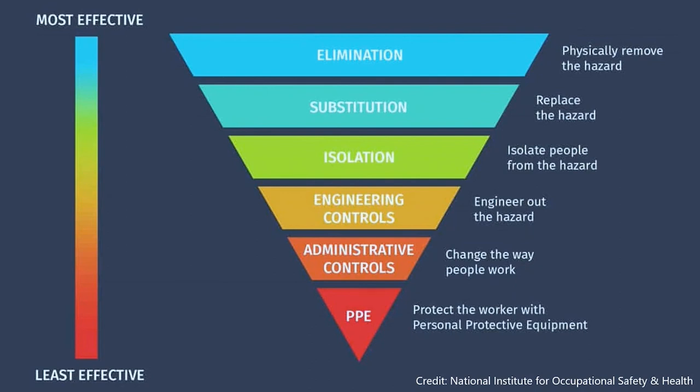What is the value of an engineering control in terms of its independence and its probability for failure on demand as opposed to an SOP and operator intervention? What is the benefit to having a process that is designed with no operator intervention at all, and everything's done remotely, and can we get credit for that we may not be taking advantage of? Those are the kind of decisions that LOPA can help you with, because it can actually put some numbers to it. So it's not just your judgment, your opinion, but you can actually see the value and can compare different control technologies one against the other and how effective they are.